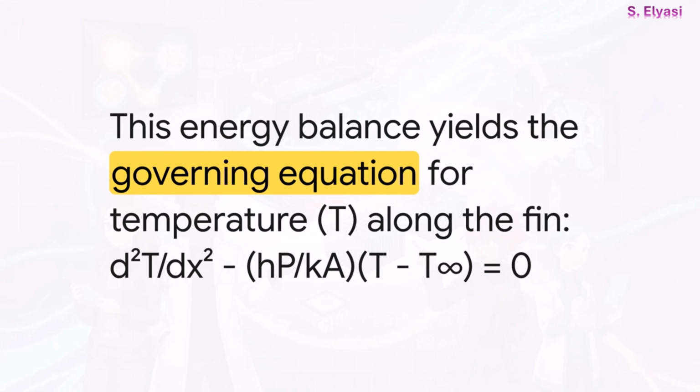And that simple energy balance, when you write it in the language of calculus, turns into this: the governing differential equation for the fin. Now don't worry, don't panic. We are not going to solve this today. What's so important to see here is that this one single equation tells the fin's entire story. It can predict the exact temperature at any point along its surface, just based on its material, its shape, and the air around it. It's amazing.